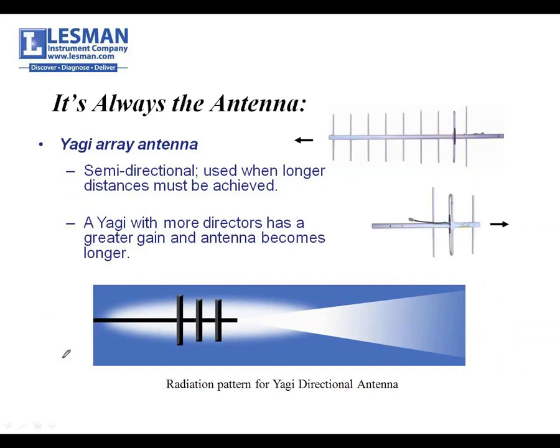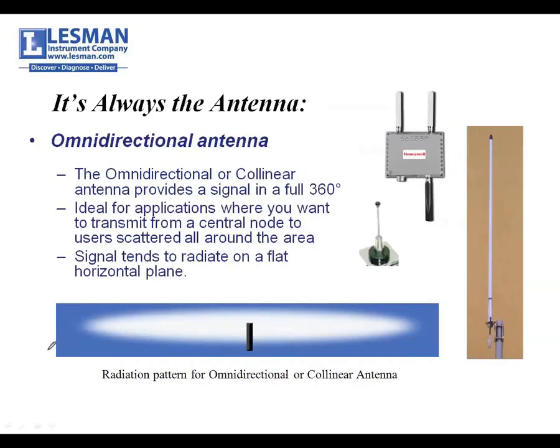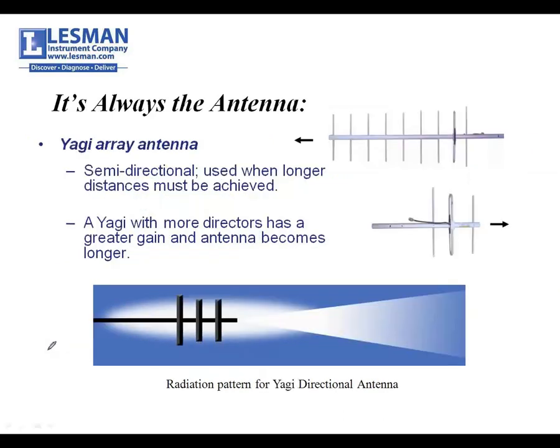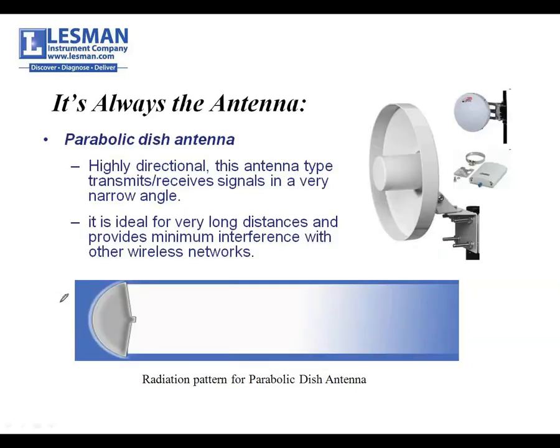So we like to use Yagi antennas in environments where we're doing a multi-point out on a perimeter to a point in the middle. So you aim the Yagi antennas to one of these Omni antennas in the middle, which is broadcasting in all directions. And the beauty of the Yagi is it gives you good, strong connectivity, but you don't have any energy coming off the left side or the back side, so you're not inviting in radio energy from your neighbors. So it makes for a nice, robust environment when you're working in that design.